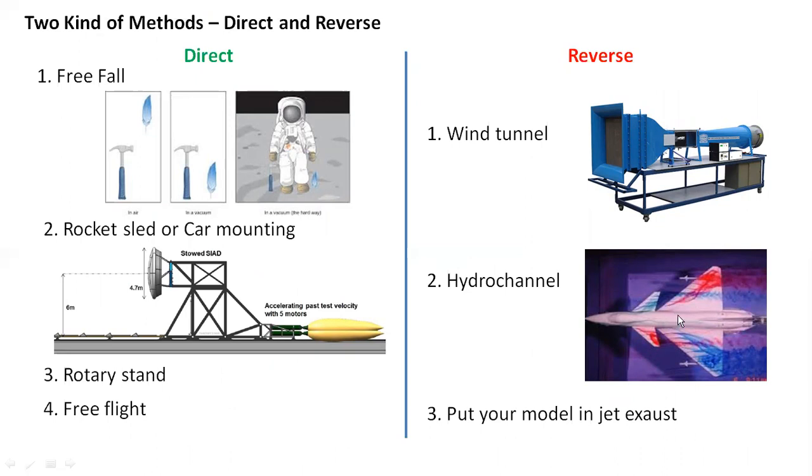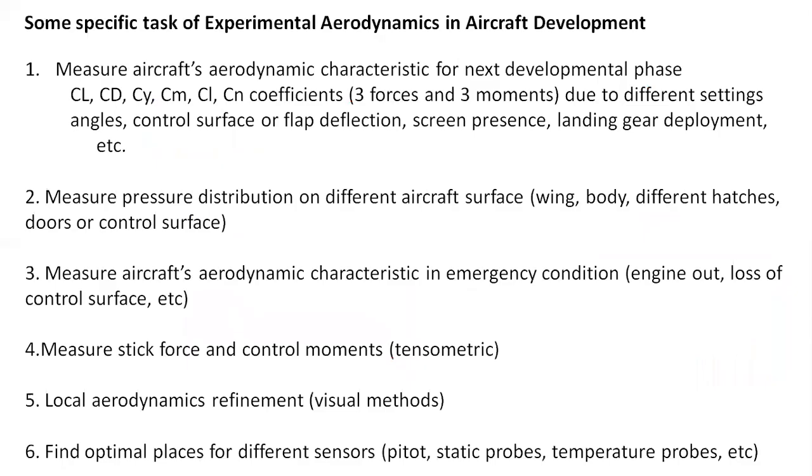We put paint in fluid, and this paint shows us the direction and trajectory of fluid movement. We can look at these pictures and say, this is bad, this is good. For example, here we must change the shape, add some surface, and so on. We put a small change in the aircraft shape and look at the trajectory of the air and make a decision about good or bad shapes of some part of the aircraft.